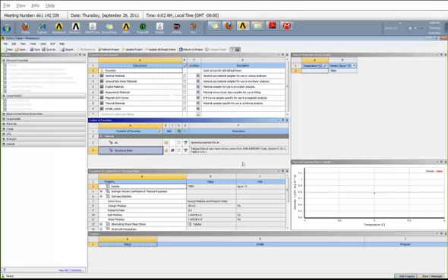So within that material library, you will have all the nCode material library, which basically has two sets of material properties, one set for your strain life and the other set for your stress life. And to add any material to your model, you would just click on this plus symbol over here, like the one that you do in a normal static structural analysis.